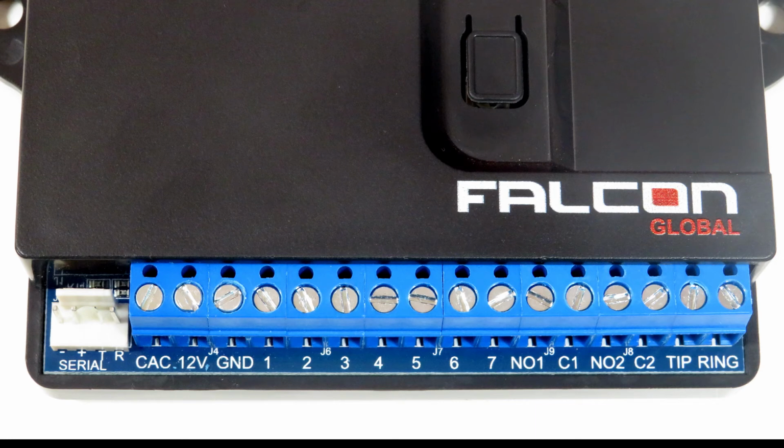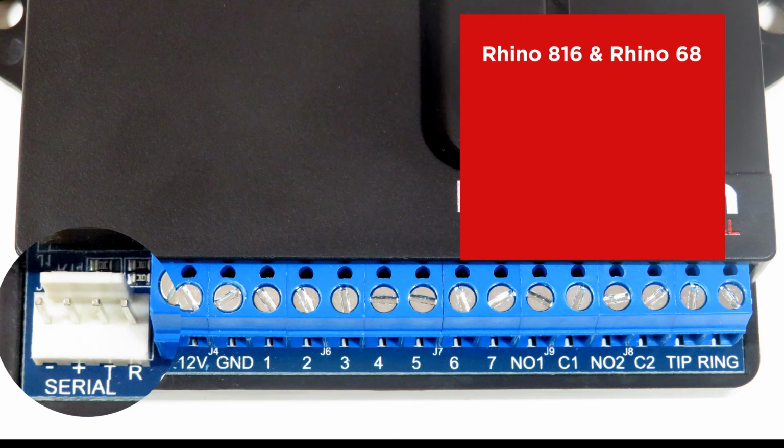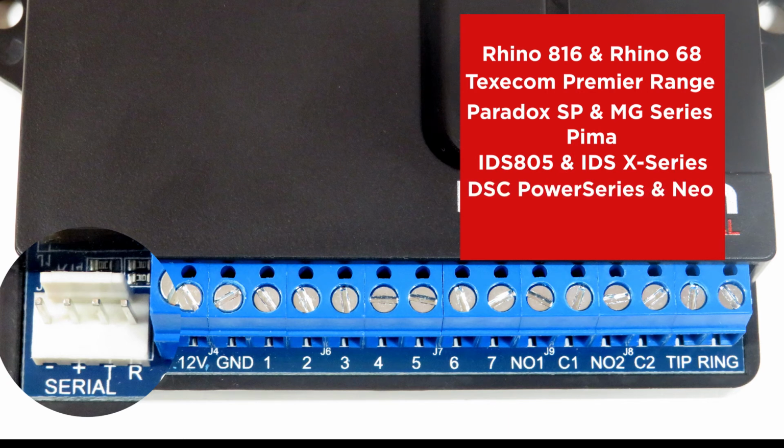There are 3 different ways to connect the Falcon to an alarm panel. The first way, which we recommend, is through the serial port, which supports the following panels: Rhino 816 and Rhino 68, the Texecom Premier range of panels, Paradox SP and MG series panels, PIMA panels, the IDS 805 and IDS X series, the DSC Power Series and Power Series Neo, as well as the Risco Lightsys 2.